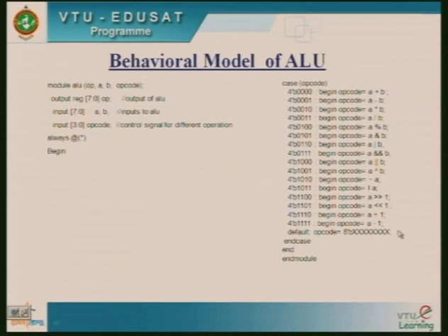I can then give one more condition as default, with XXX, which is nothing but non-determinant. I will close this case statement using endcase, close the begin statement with end, and close this module with endmodule. So this is the behavioral model of the ALU.